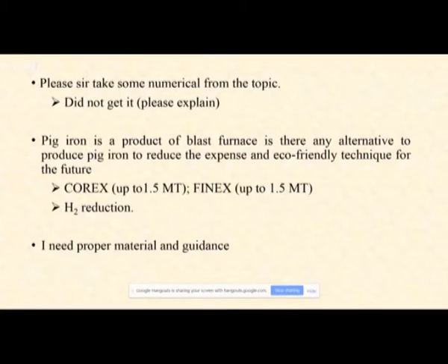But certainly they have some advantages, especially Finex, because you can directly use coal instead of coke, and you can use the fines. So you are removing many other ancillary units in between. But there is still a long way to go for this technology to compete with the blast furnace.